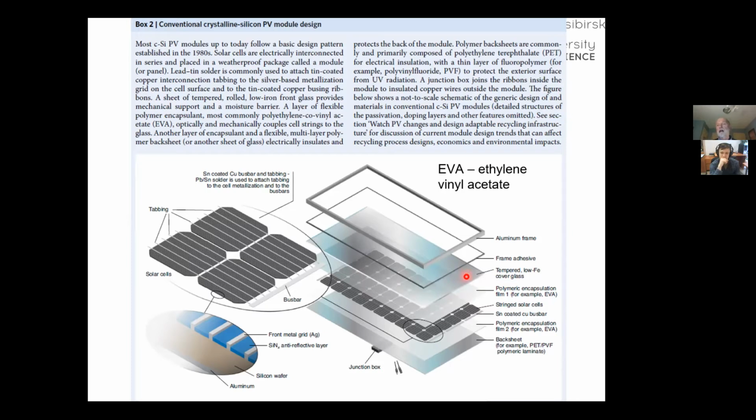There is a slight disadvantage in having a glass cover, because any glass cover can cause a greenhouse effect. The longer length radiation that isn't absorbed by the PV modules and gets reflected actually gets trapped by the glass. So the glass can have an adverse effect on the module or the cell temperature. But the frame and the glass, they're relatively easy things to recycle.